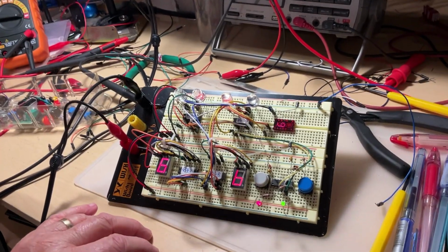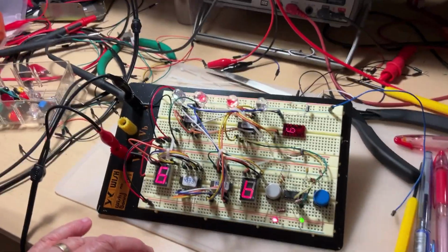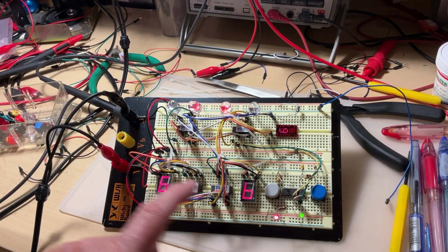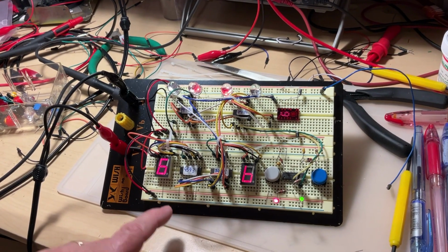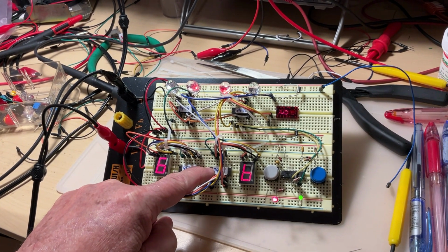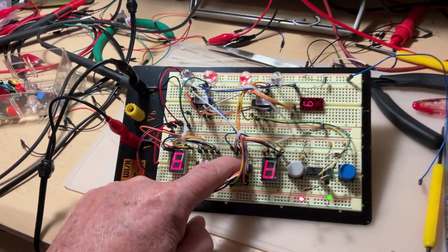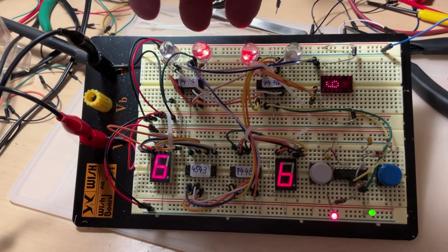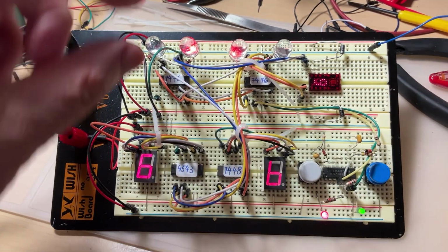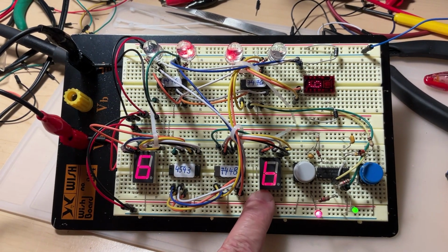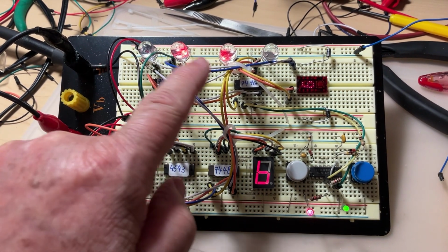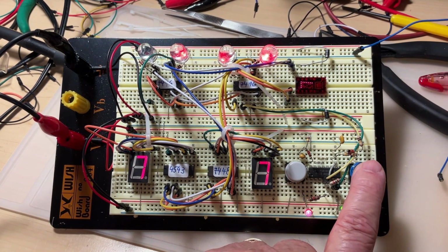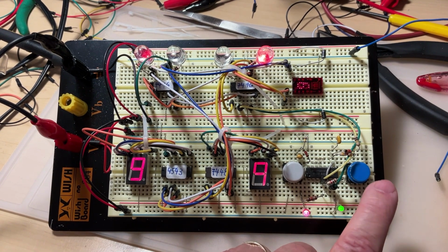What is the point about having a different, let's say, format for the two displays? Again, there's the combinational circuit inside the package, inside the decoder. So when the decoder receives the 4 inputs, the signals coming from the 4 outputs of the flip-flops, it converts these signals into the appropriate number displayed right here. Like 0, 1, 1, 0 is 6. And let's go further. 7, 8, and 9.